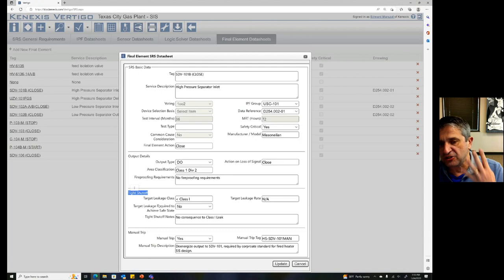So as we saw, this valve is used in 4 safety functions. So if you use that ungodly, horrible checklist approach to creating safety requirement specifications, you're going to need to recreate this documentation for 4 different safety functions because you use this valve in 4 different safety functions. Just run away from that garbage. This is the right way to do it.